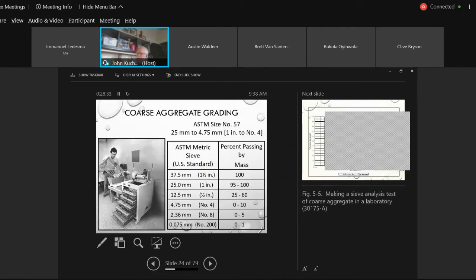This is just a big Gilson sieve shaker. Okay, that's why when we did sieve analysis last year with Natalie, you guys and my groups, we do not do a sieve analysis in accordance with CSA or ASTM standards as far as the minimum mass of aggregate. For sieve analysis with 20 millimeters, your sample should be minimum 5,000 grams, 5 kgs, minimum. We have one of these sieve shakers in the back, as you're probably well aware of. That's what all the independent labs use.